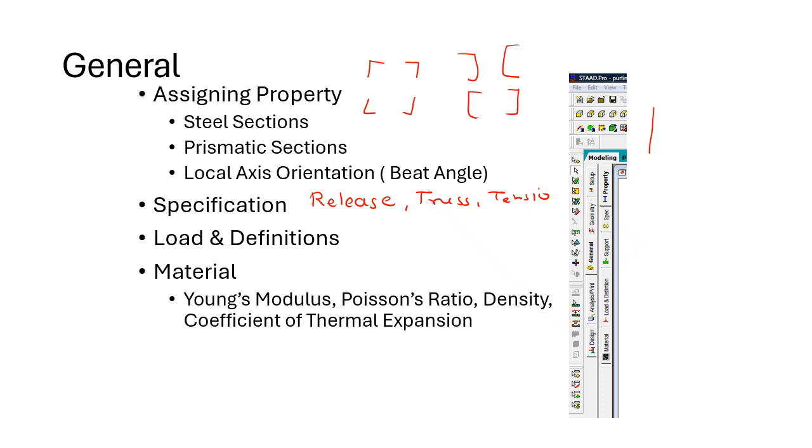Then come loads and load combinations. We can define our loads, different load cases 1, 2, 3, and it has inbuilt wind and seismic loads for all the international standards. In seismic, again, we can do both equivalent static analysis and response spectrum analysis, and it has the capability of performing time history analysis, also linear time history analysis.